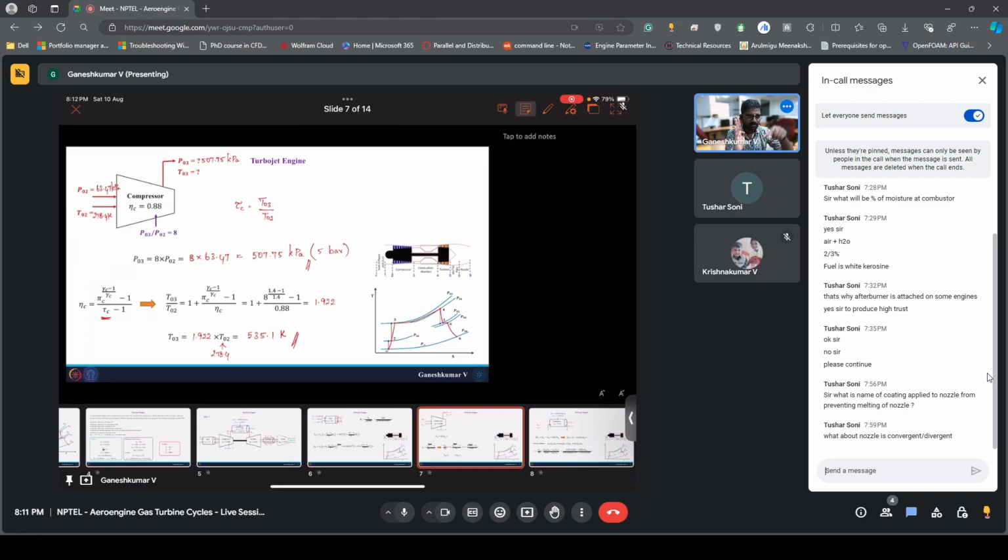Since it goes up and down, it is like a continuous, what do you call, fatigue. It can undergo little fatigue failures, a few microns over there. So what people usually go with is a new technology: they try to develop this entire blade with a single crystal. They do crystal growth and try to make the entire blade, so they will not do any machining process. Instead, they try to grow this blade with a single crystal, so that there won't be any crack present in the microstructure.